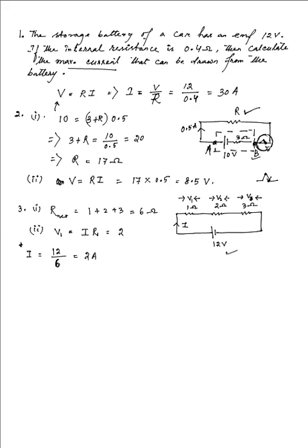Now 2 amperes is the current, and the resistance of the first one, that is R1, that I have written over here, is simply 1 ohm. So you have the voltage to be equal to 2 volts. And similarly, you can calculate V2 and V3, because in case of series combination, the current across each of them will be the same. In case of V2, you have I times R2, where I is simply 2 amperes that was calculated, multiplied with 2 ohms being the resistance in this case, and that is equal to 4 volts. And similarly, V3 you can obtain to be 6 volts.